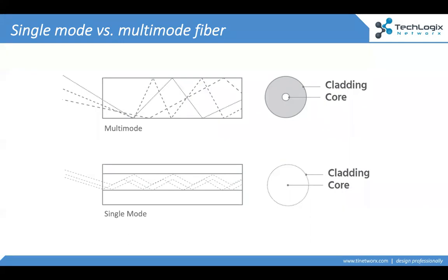Now, at the end of the day, people will ask me, well, which cable should I pull? Give me one. I don't want to have both. And the answer is single mode is becoming the predominant cable because it's that do-all, go-anywhere cable. My advice to folks is, look, it's going to take you an extra 15 seconds to terminate, but it's the same tools, same type of connectors. It's not like you're tooling up differently.